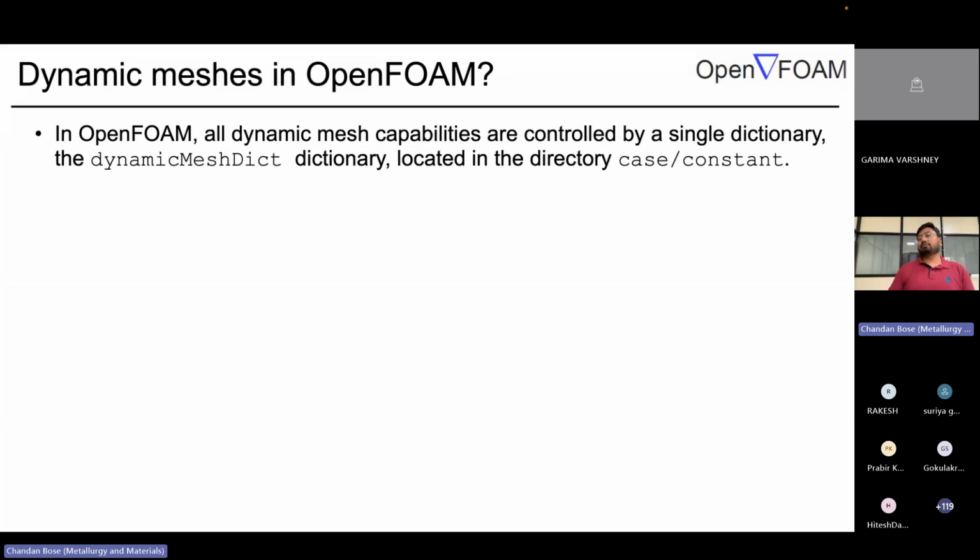We have a constant folder where we keep all the data that remains constant throughout the simulation, such as mesh files. In the polyMesh folder, we have transport properties. And in system, you have seen we have controlDict, and other files such as fvSolution, fvSchemes. And if we want to do a parallel computation, we need decomposeParDict.